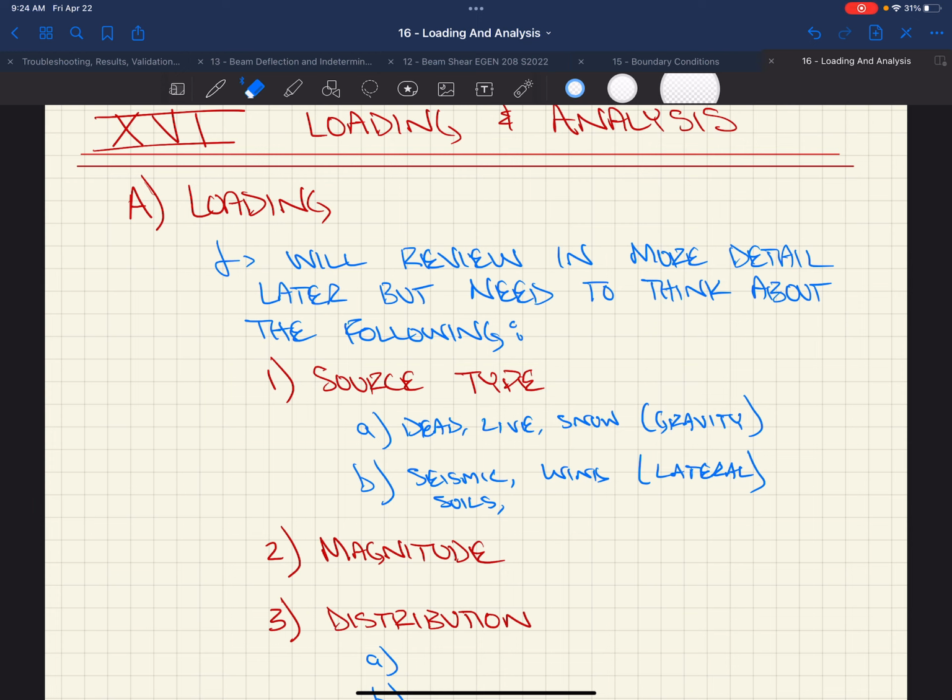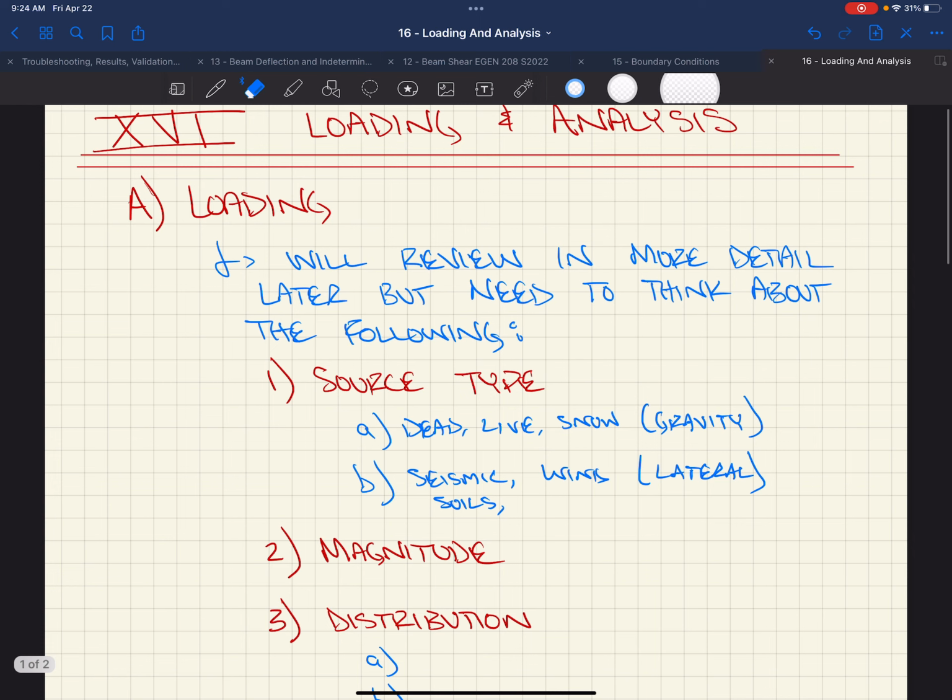Well, if we're doing overturning, we might say that this building's brand new and it doesn't have any collateral load, right? And so if we're looking for the worst case, say uplift, we might ignore it, okay? But then down the road it might be there, so then we might include it in the seismic calculations, right? And so we have to think methodically about what load combinations we should add it in, what load combinations we should pull it out of. When is it there? When is it not there? So I just say collateral.